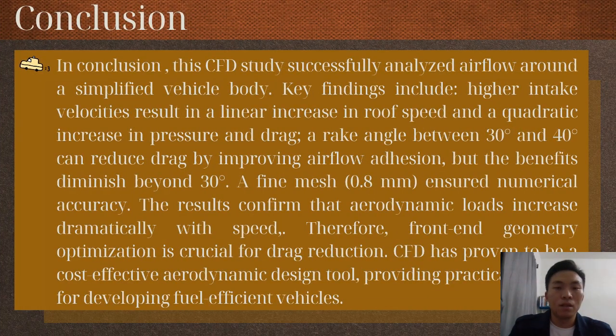In conclusion, this CFD study successfully analyzed airflow around a simplified vehicle body, and the key findings include: higher intake velocities result in a linear increase in roof speed and a quadratic increase in pressure and drag. A front angle between 30 degrees and 40 degrees can reduce drag by improving airflow adhesion, but the benefit diminishes beyond 30 degrees. A fine mesh of 0.8 mm ensures numerical accuracy.